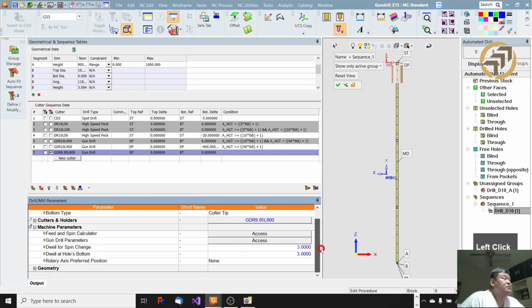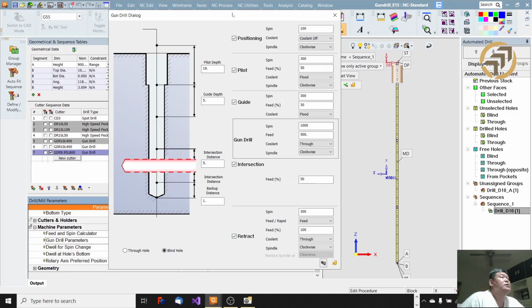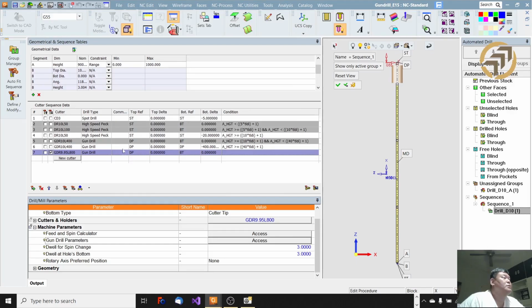And how about the settings? Yeah, we need to change some setting now. This is what we need to change, right? So previously we made a pilot hole by gun drill 400 mm, so I'll put maybe 399, right? The rest is the same, so save. Then we'll put conditions.